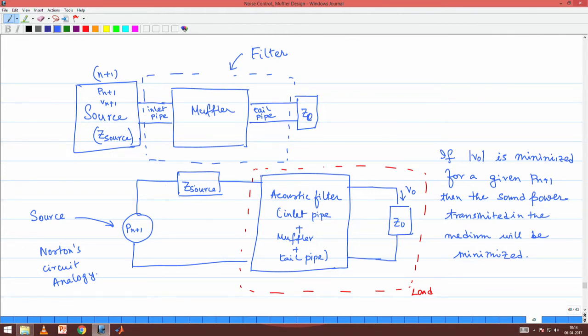So, if we wish to study the situation where source impedance is very low, then you can have this circuit to your help, because that will be easier to interpret, whereas the interpretation for a very large source impedance can possibly be better with this modeling, because when the source impedance is very large, this will be made an open circuit. See, this will be a current source with an open circuit in the shunt position, and that will have a very interesting special cases.